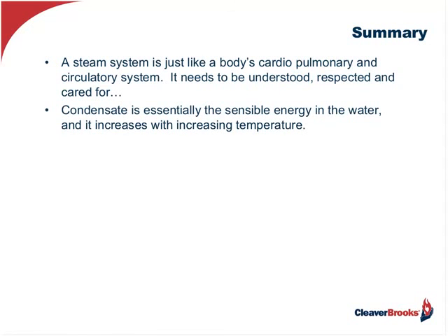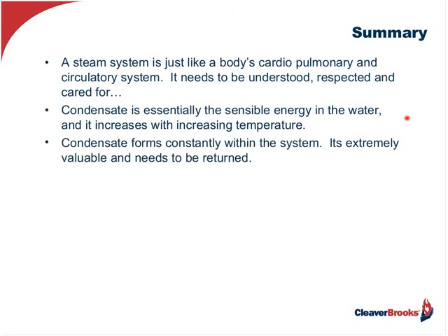Condensate is essentially the sensible energy in the water, and it increases with increasing temperature or increasing pressure. So as the pressure goes up, the amount of sensible energy that I have to add, which is condensate, is increased. Condensate forms constantly within the system. It's extremely valuable and needs to be returned as much as possible.